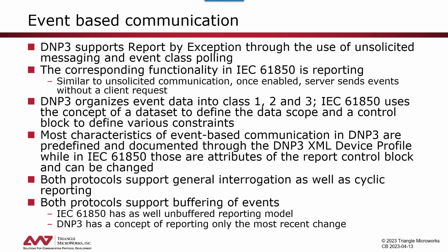IEC 61850 has as well a non-buffered reporting model, while DNP3 has a concept of reporting only the most recent change, where we don't have exactly the similar concept in 61850. There we use more the unbuffered reporting when we don't need the events.